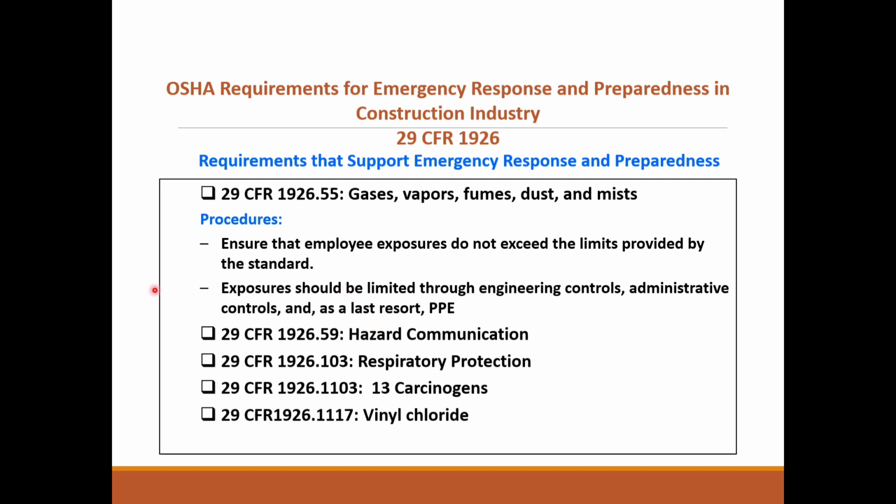Based on the 29 CFR, gases, vapors, fumes, dust, and mist. Ensure that employee exposure does not exceed the limit provided by the standard. That's why we conduct gas testing, guys. The exposure limit should be kept low enough. Engineering controls and administrative controls first, and the last resort is PPE. That's why always rely on them first, guys.